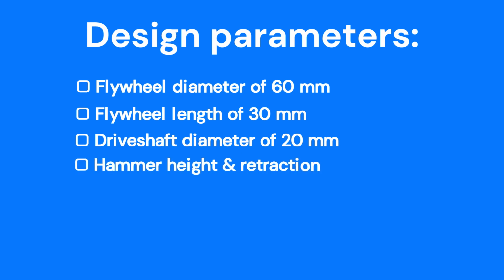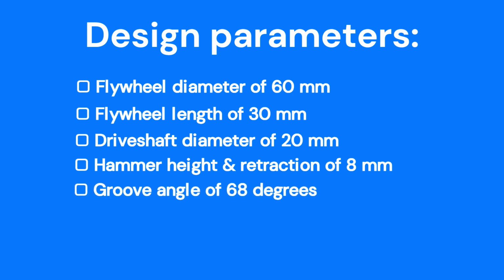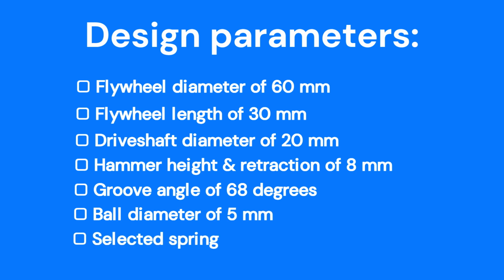A hammer height and retraction of 8 mm. A groove angle of 68 degrees. A ball diameter of 5 mm. And we selected a spring with a preload of 210 Newton corresponding to 10 mm deflection.